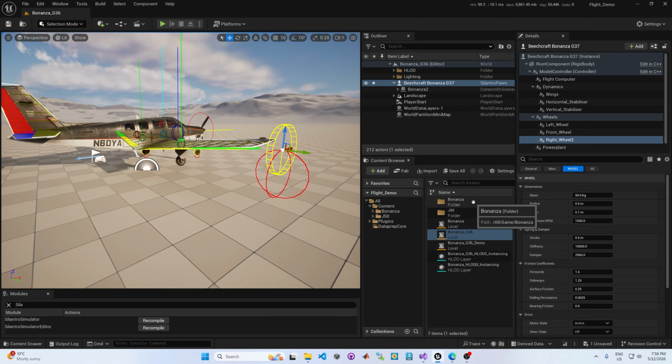Inertia is for a given amount of moment application. A wheel with a higher mass is going to have a higher inertia, which means for the same amount of moment, the acceleration is going to be lower. If you think of the F equals ma Newton equation, the more mass you have, the lower the acceleration for the exact same amount of force. This is just a rotational form of that. So if I set the mass to 900 kilograms, on the same aircraft, applying the same force and generating the same moment, this wheel is going to roll slower than the one we had set before.